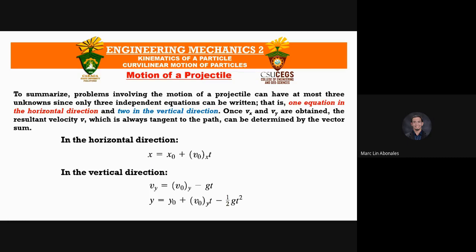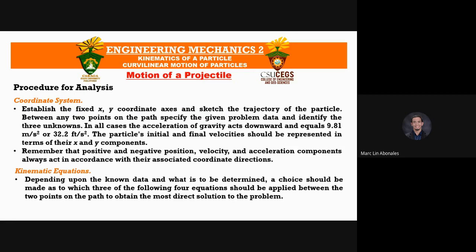So just a procedure for analysis, when we solve the motion of a projectile, it is the same as with the rectangular components in our previous topic. We start by establishing the coordinate system. We establish the fixed XY coordinate axes, and we sketch the trajectory of the particle. Between any 2 points on the path, you specify the given problem data and identify the three unknowns.